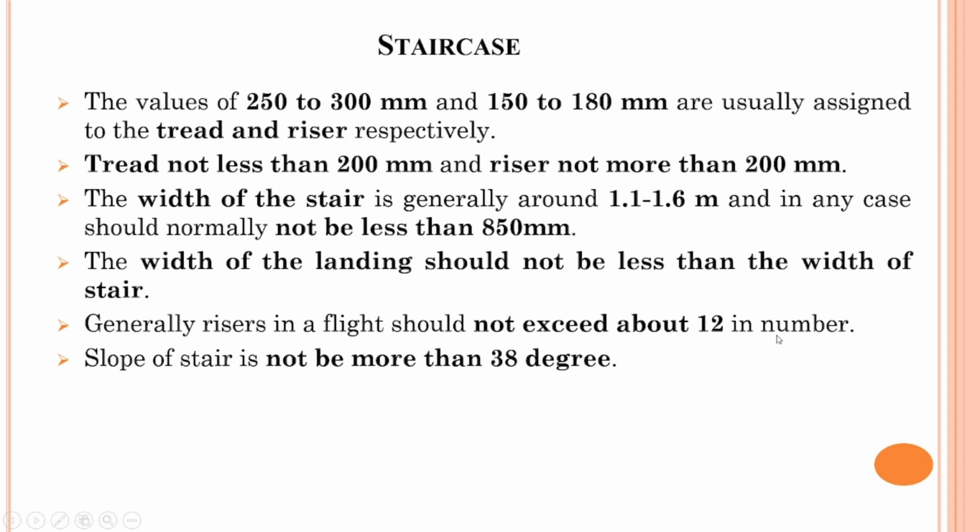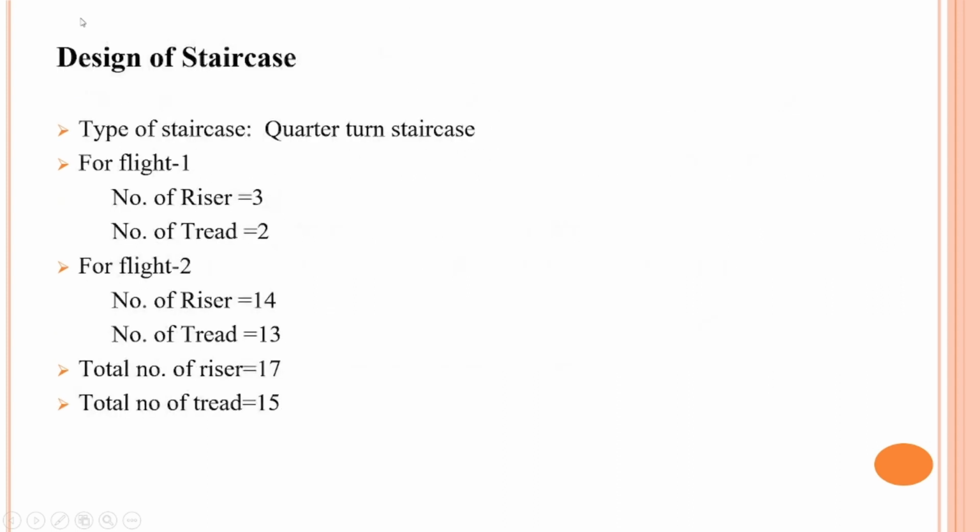How many flights you have used: you should not exceed 12 risers in a flight. Like this, you have to do this specification. You have read this staircase and its result.